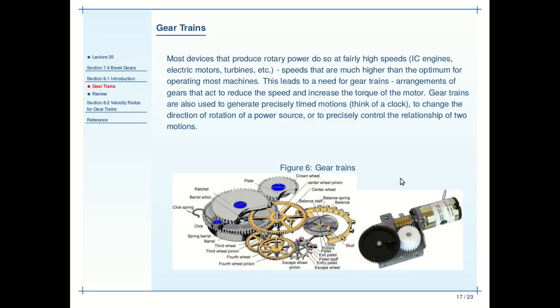So, anyways, here we have a couple of gear trains. This particular one probably looks fairly intriguing. It's got a worm gear, or excuse me, a worm that's rotating a worm gear. That worm gear then is directly rotating a secondary gear, so a fairly high gear reduction. Over here we have a very complex kind of gear train. This particular one is coming out of a clock or a watch, but they're both gear trains.